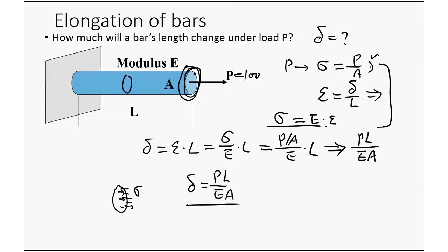Now, under what condition can you use this equation? Hooke's law. It has to be linear elastic. What does that mean? That means small deformation. Deformation must be small, the load should be small enough, and it should be a linear elastic material. Most engineering materials in the small deformation range we can always treat as linear elastic. So you can always use it. Basically, for the problems we give you, you can always use it, because we assume all linear elastic.